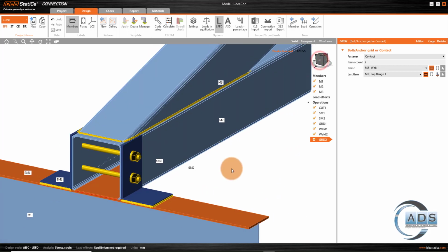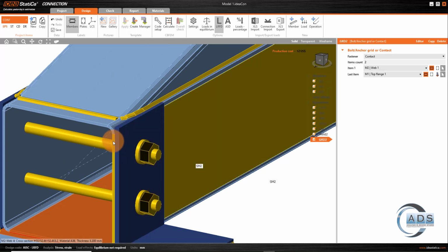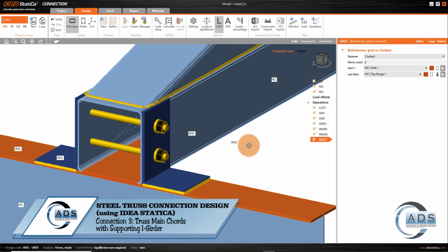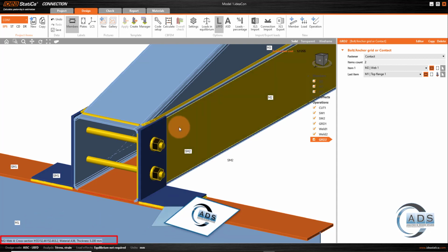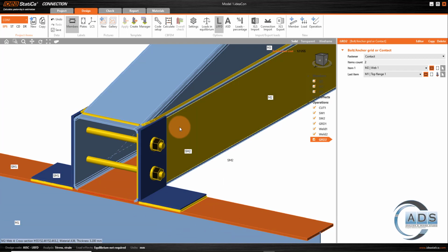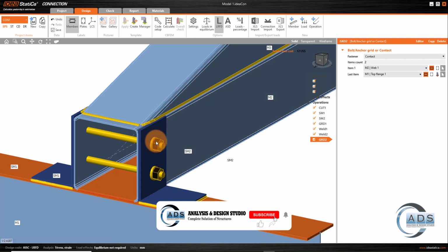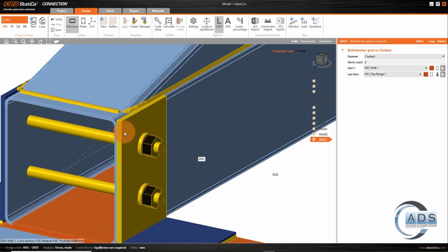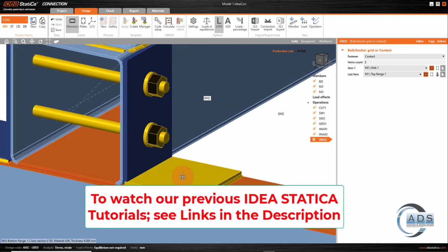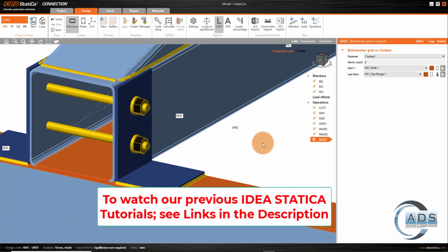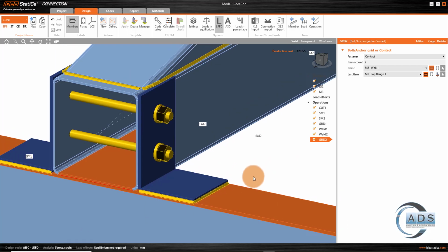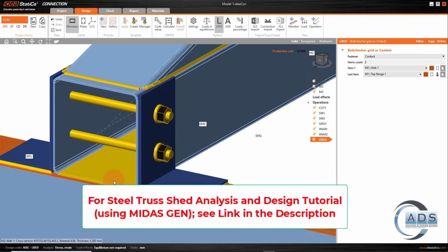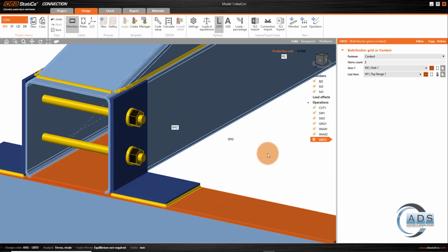One question arises here, why are we not providing the contact between this plate and this plate, similarly between this plate and this plate, and so on? Because let's say SM2 web 1 and this M2 web 4 are in contact as well, but this contact must be built up by these bolts. Since we are using the bolts, it automatically takes care of the contact between these 2 plates, similarly between these 2 plates. And since we are using the welds here, it is understood that these 2 plates are in contact through this. But we did not use any operation to tell this software that these two plates are in contact. Alright, so we have to create the operation named contact.